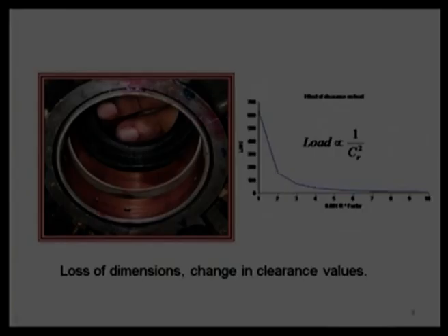So, from 625 Newton to 150 Newton, that is a substantial change in load carrying capacity. The component is bound to fail in that case. It was working in a hydrodynamic domain and suddenly started working in a boundary lubrication domain. That is a huge variation in friction, performance will deteriorate, support will decrease, and it may cause failure of the whole system.